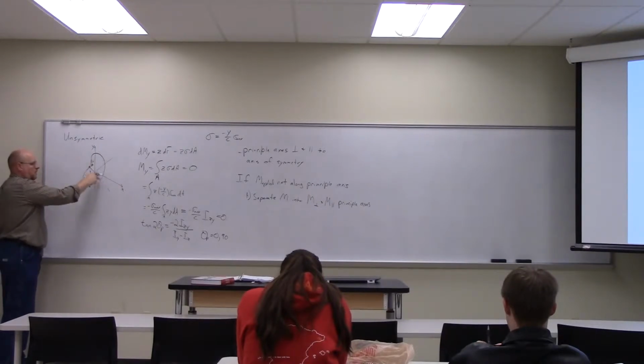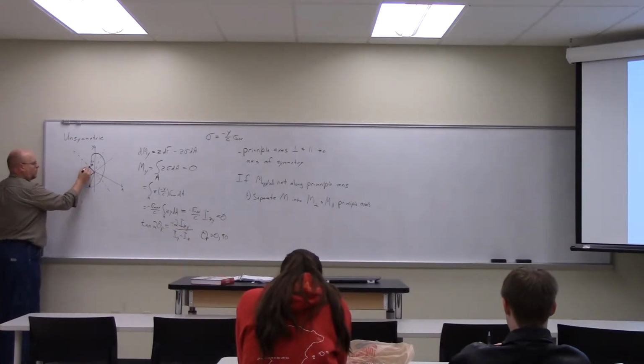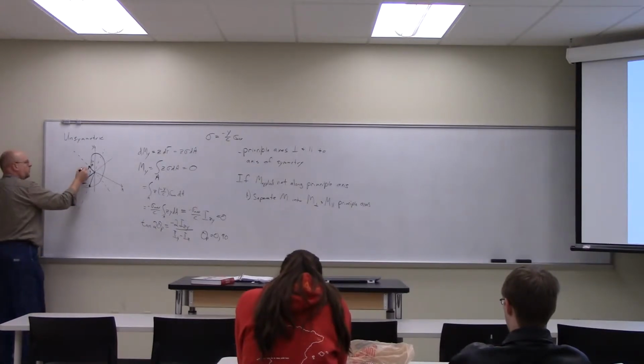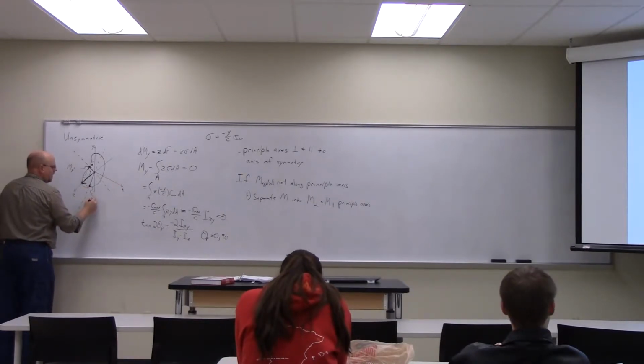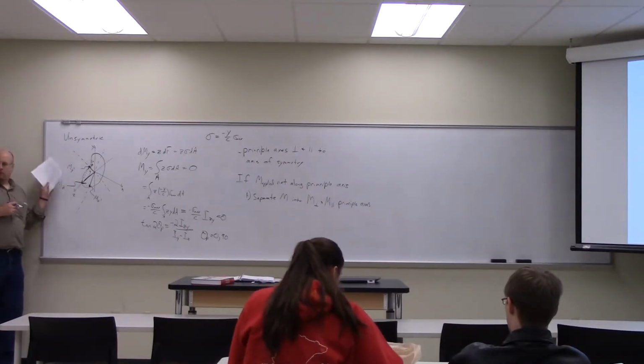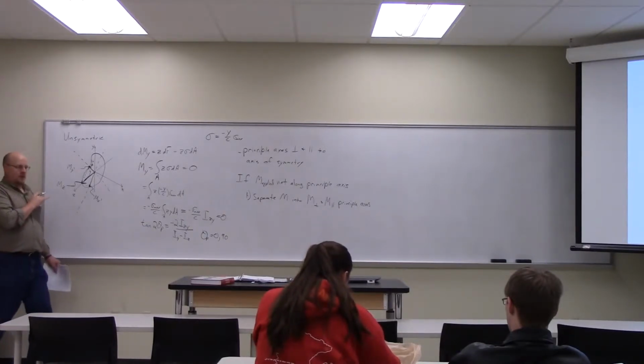but the principal axes are here. Those are the principal axes. So I take a component, figure out what's the component of the applied moment along that principal axis, and the component along this principal axis. Okay, so I call this piece M y prime, and this piece M z prime. Of course, what I applied originally was just Mz along the z axis. Where y prime and z prime are the principal axes. Okay, everybody got that? Clayton, still?